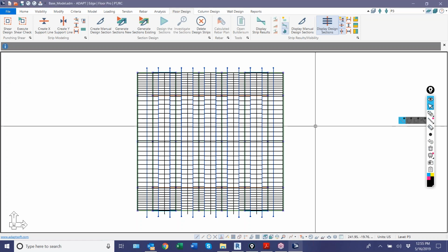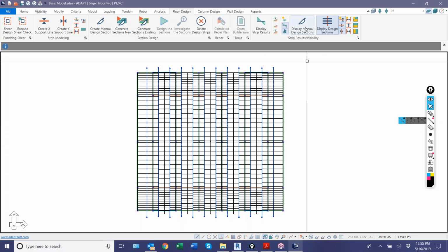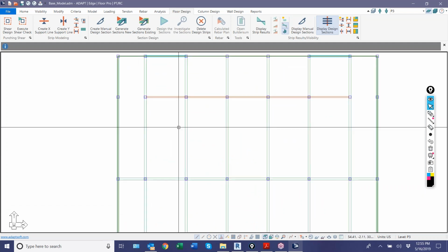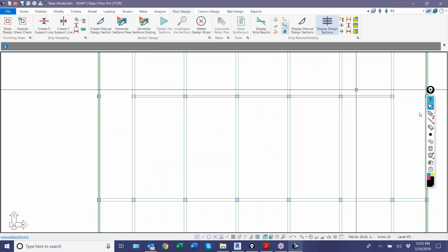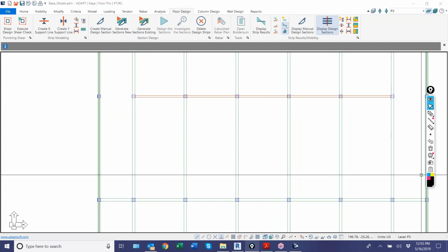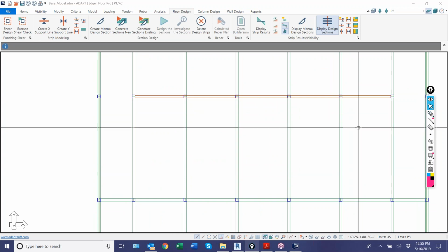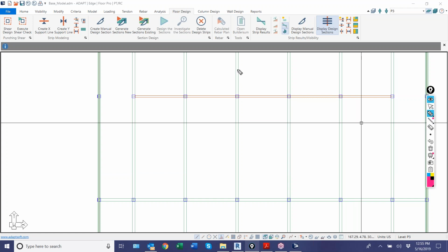I guess the downside to modeling it as a continuous support line would be, let me turn off the strips here, if there's a true break in the slab here, and in the end the result you want is maybe not post-tensioning, but PT and rebar, and you say, okay, well, I want rebar. If it's continuous, the rebar would technically be shown graphically like this, passing through that joint. If it's split, then you'll basically have two rebars. You'll have one here and one here. So it's more true to representation if you break the support lines.